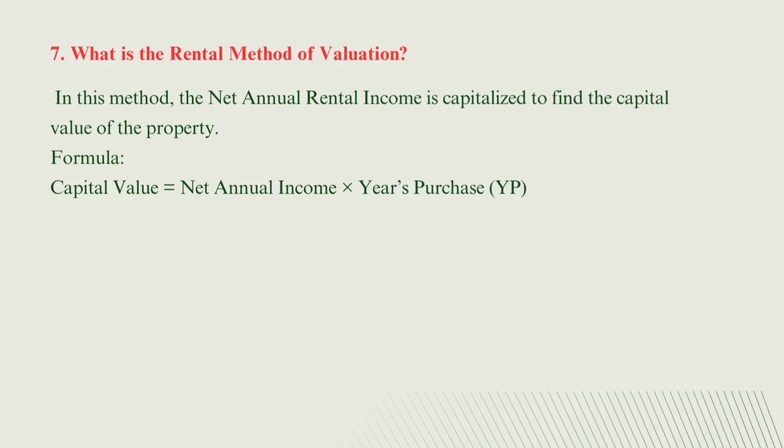Now the next question is, what is the rental method of valuation? In this method, the net annual rental income is capitalized to find the capital value of the property. It is given by the formula capital value is equal to net annual income multiplied by the year's purchase. Year's purchase in short form is YP.